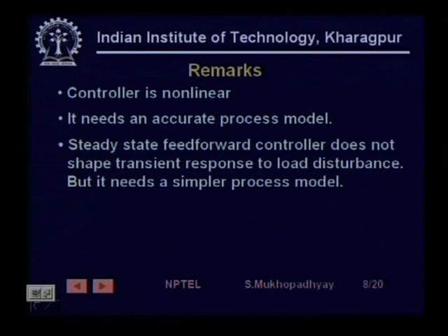And see that at steady state, if you have a step input in Ti, there will be a step change in Q, but a step change in Q may not exactly match the response of the temperature in the tank. That is, there may be some transient, and from instant to instant it will not be able to match the temperature.